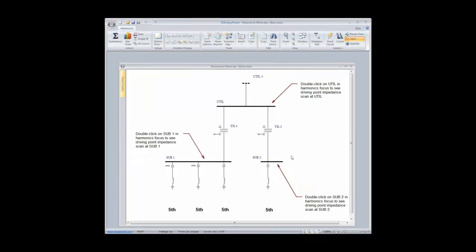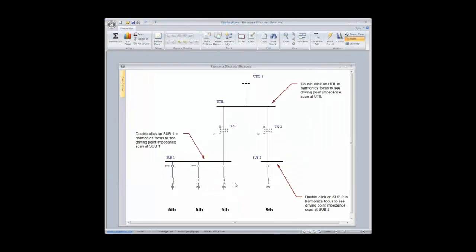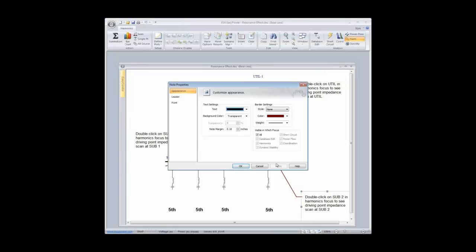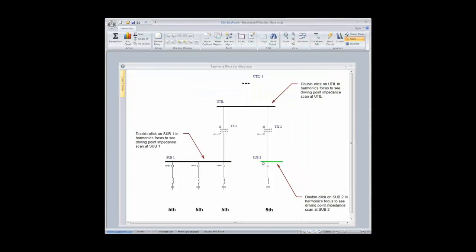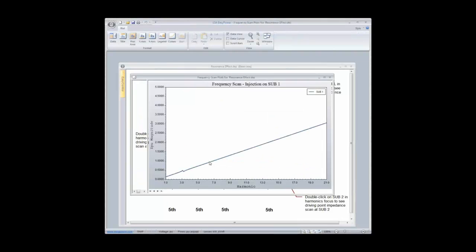And that's really important also if you're applying one over here. The effect of the other filter has been changed. It's modified as you're seeing it from this location. Let's do it another way. Let's unclick this filter, look at this bus, and whoops, that's that note right there. And again, we see the nice fifth harmonic filter. From this location, what do we get?